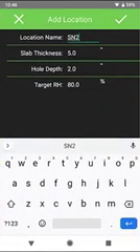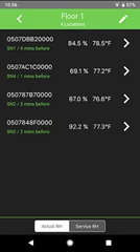On the Add Location screen, give the new location a user-friendly name. The other details on thickness, depth, and target RH are preset according to the sensor map default values, but may be adjusted accordingly. The bottom right icon on the sensor map screen brings up the View List screen that lists all the sensor locations for that sensor map.